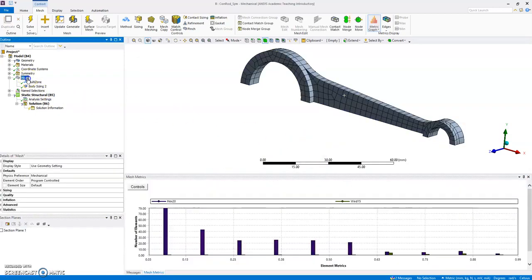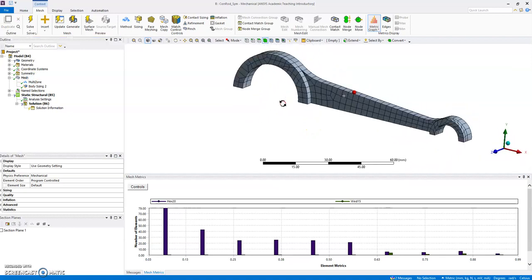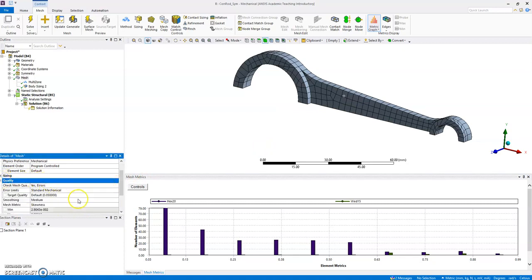That's not surprising. There are some bits of prisms, and we'll see where in a minute. Okay, let's look at the mesh. Oh, that's quite a lovely mesh, isn't it? Quite a lot nicer. So what was our quality metric? The quality metric was skewness. Oh yes, 0 and 1. Okay, and we have got 2 types of elements, already nicer than the X dominant. Some wedges and some bricks.